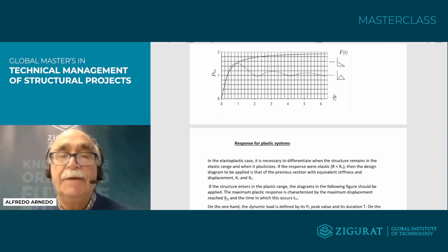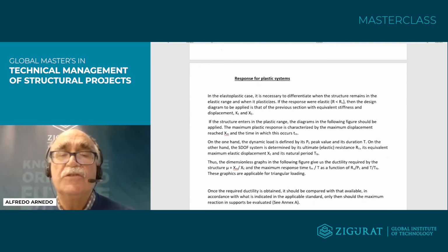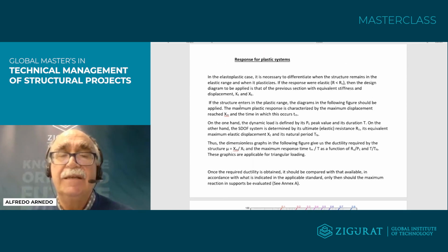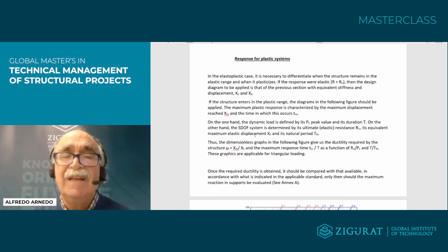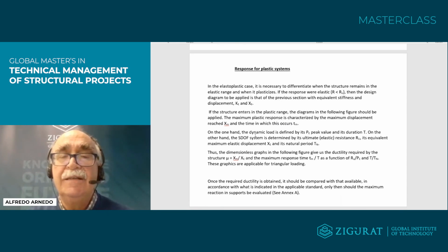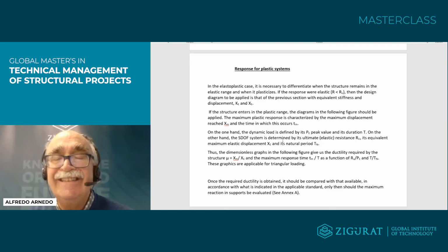So for linear behavior and a long duration, the maximum dynamic load factor is 2. When we exceed this proportion, the response is in the plastic field. In the plastic field, we have to consider the response of the structure when the structure has reached the maximum resistance.